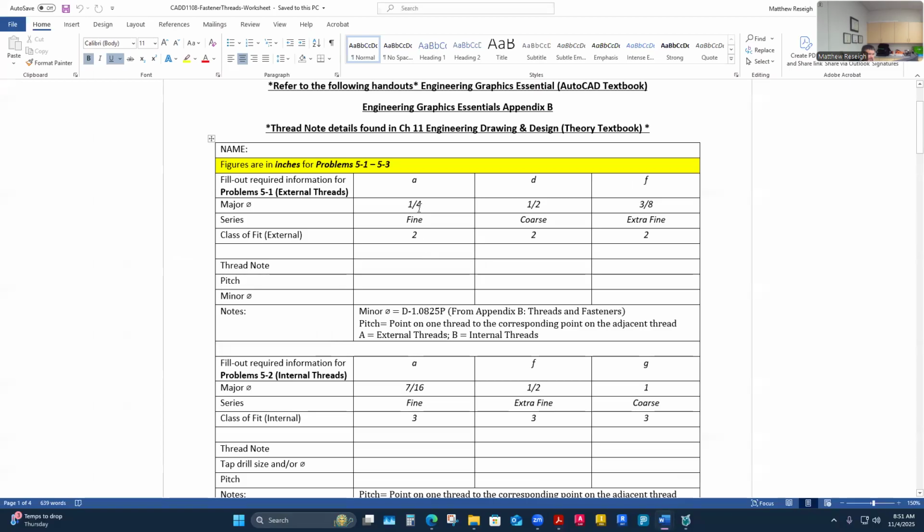In this particular case, it's given us the major diameter is 1/4 inch. It says that we're in a fine series. So we'll look at this on our chart. It'll show us there's maybe three different categories: a coarse, a fine, and maybe an extra fine on some fasteners. Not on all, but definitely fine and coarse on most unified American-made fasteners. So we're definitely a unified, I think they call it unified, for standard fasteners. So this is 1/4 inch, our regular USA sizing here. 1/4 inch major diameter, in a fine series.